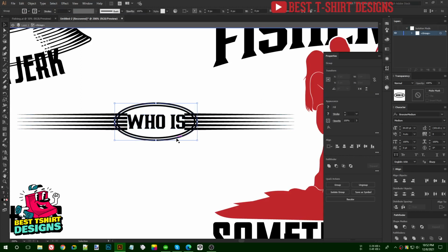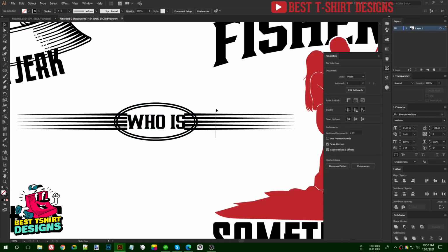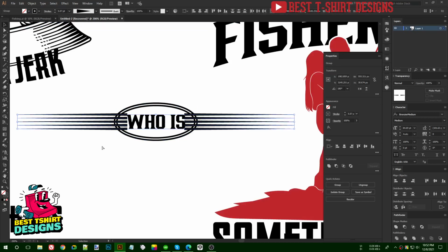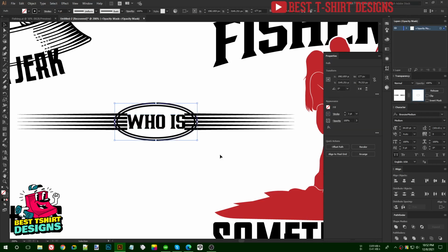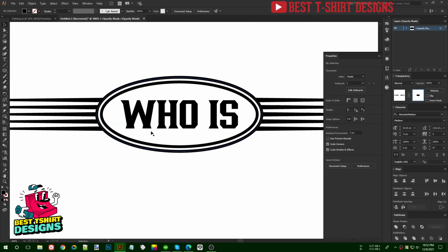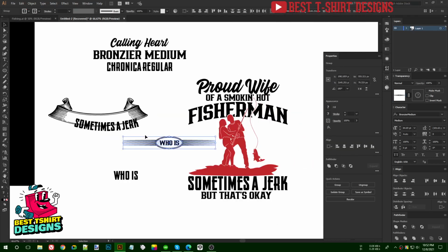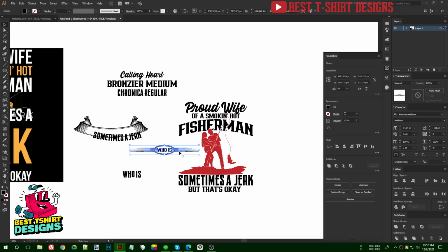Don't worry, just select this outer ellipse and copy that. I'm going to select this one and this one, make them a group, then open transparency and press Ctrl F here. Ctrl F will paste it here, and then press Shift X. Shift X will make it a fill color, and whatever is in black fill makes that area hide or become transparent, whatever you call it. So I'm going to expand everything here. That is good. Let's group them.